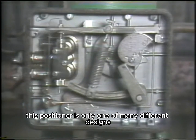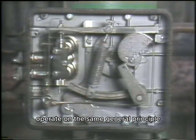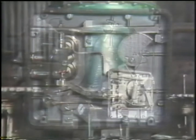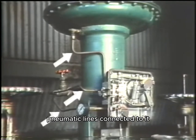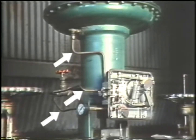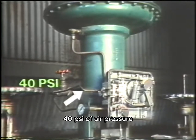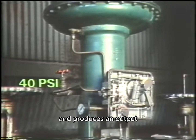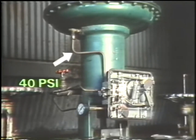This positioner is only one of many different designs. All positioners, though, operate on the same general principle. They use a small pressure to control a larger pressure. In this example, the positioner has 3 pneumatic lines connected to it. This line supplies the positioner with a constant 40 psi of air pressure. The positioner regulates this pressure and produces an output that is supplied to the actuator through this line.